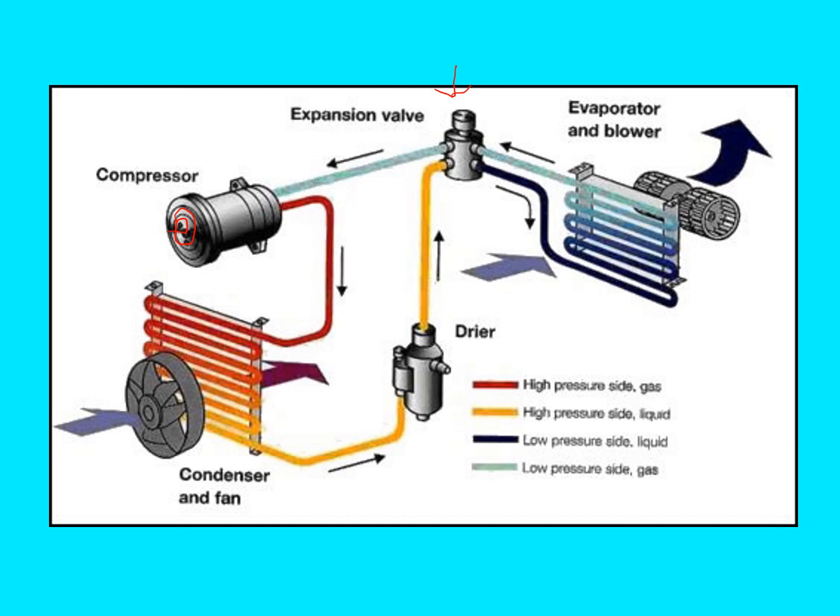So from there, the high pressure liquid is flowing into a receiver dryer. It leaves the receiver dryer as a liquid. And then we get to the TXV valve. So right here, we have high pressure on this side coming up to there. Right after that is low pressure liquid going into the evaporator.